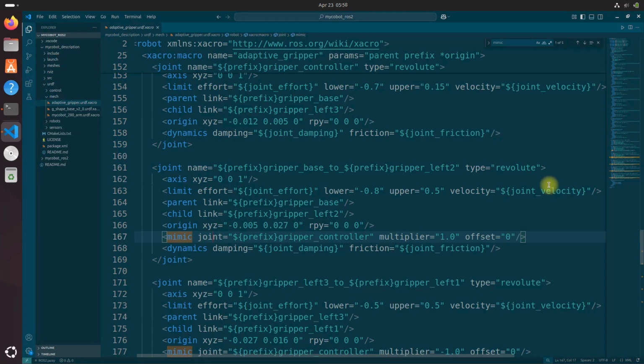Remember, that was defined way up above in our parameters, where we developed our XACRO property macros. So that's the limit tag right here. What are the limits of this particular joint, the motor that connects the base of the gripper to the left finger, or at least the base of the left finger, which is left 2? You've also got left 1 as well. There are 2 components of that finger there.